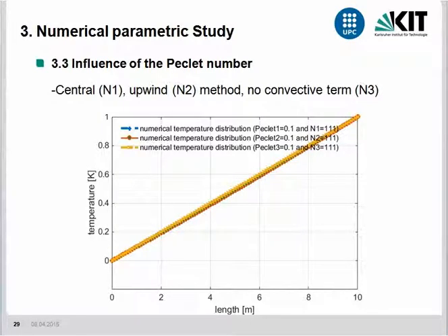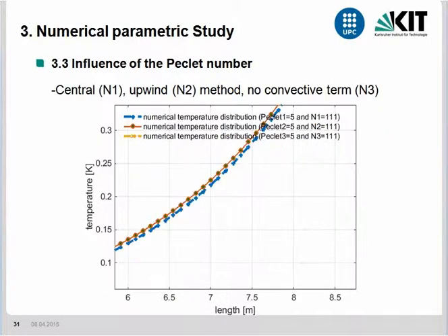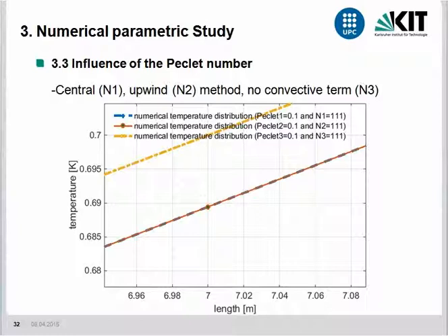In the case the Péclet number goes to 0, the curve approximates the distribution of the non-convective case. If Pe is negative, the temperature increases. The difference between values of the upwind and the central difference method occurs due to the diffusive characteristic of the upwind approximation. This tends to have a stabilizing influence on the numerical solution. Also, as seen, it has an adverse effect on the accuracy. The diffusive characteristic of the upwind method is also shown in the following pictures.